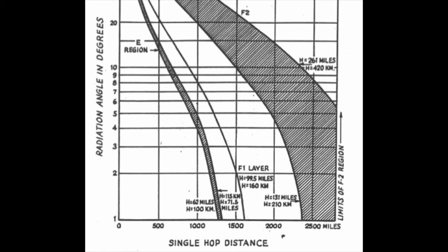You will also receive signal further away and closer away than 1,500 miles. However, the signal strength may not be quite as strong because the antenna is not designed to have maximum radiation at any angle other than 10 degrees. Because this is a hypothetical antenna we're talking about.